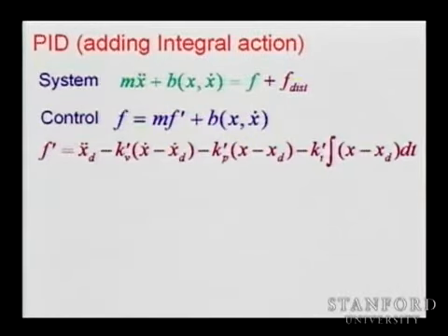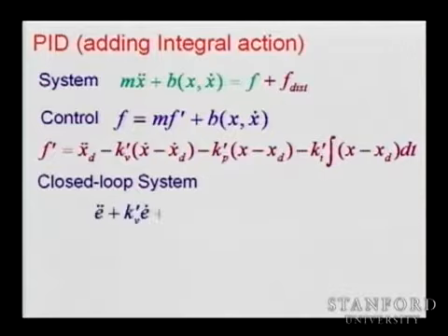Now, integral action is very good to reduce errors, but you have to be careful about the way you use it. Better to use it close to your goal position, not all over, especially if you're moving fast and accelerating. Winding and unwinding that integral might create instabilities.